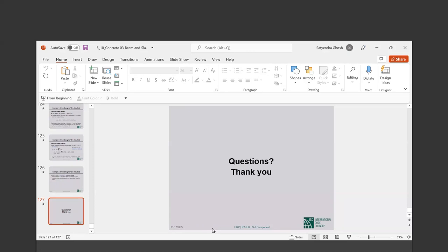Why is the first shear reinforcement of a beam placed at 50 mm from the support? I don't know if 50 is a requirement, but you need to place it somewhere. Yeah, 2 inches is what we do. I don't know that it's a requirement. It's a sensible, short distance away from the support face.